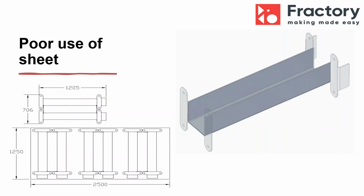And now I want to just talk quickly about an example of a poor use of sheets. This component can be seen as the channel in the middle and a few bent features around the outside. When it's translated onto one of these smaller sheets, a 1.25 by 2.5, we can see that the sheet isn't used properly. You've got big gaps in the middle, which inevitably you'll end up paying for, because the manufacturer is not necessarily going to use these gaps for future jobs, and you're going to be really uneconomical on how many pieces you can get out of the sheet.